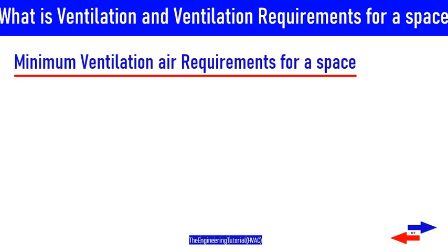The amount of outdoor air brought into a space for ventilation must be greater than the amount of air exhausted through central and local exhaust fans.